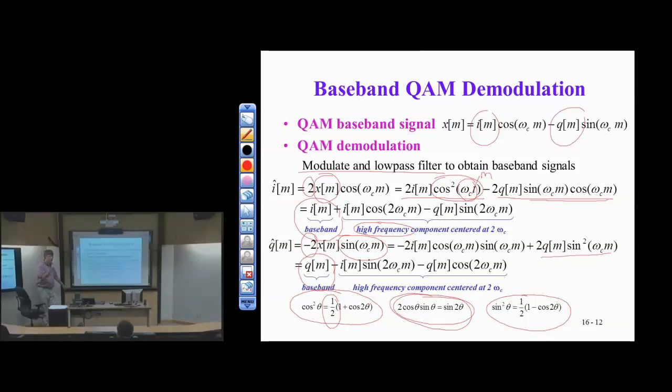It's going to do a mirror image of my constellation, which makes the constellation look the same, but the bit patterns aren't the same on that flip. You get lots of similar errors. That's when you know you missed the sign, when the receiver's just not working for anything. You're as good as randomly guessing. That's when you know something's really wrong. So this is a good place to check.